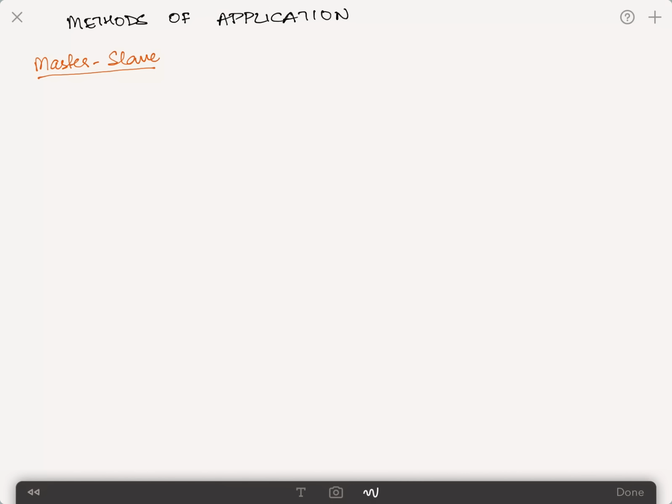You have a certain relation which is defined in a format that we did before. So say for example ui is equal to half of uk. So you can write this as ui minus half uk is equal to 0, which is your multi-point constraint condition. And when you want to now modify your displacement vector to get to the modified equilibrium equation, then one of these nodes has to be defined as a master, the other one has to be defined as a slave.